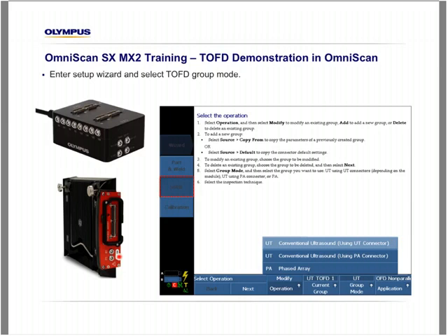When a second or third group is required, or if the TOFD is being generated from an accessory driven through the phased array connector here, we're going to select the UT conventional ultrasound using the PA connector. The main difference between these two is the voltage and the high definition independent UT board that we can generate the TOFD group with using the UT connectors here.